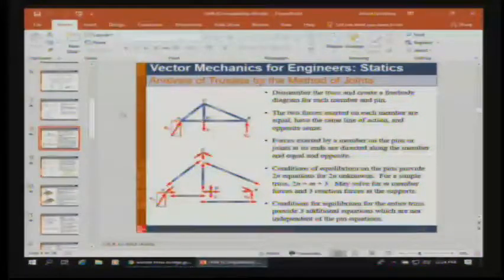All right, so when we talk about the analysis of the truss, what we're saying is that if you look at a truss like this, every one of these structural elements, AC, CD, CB, DB, and DA, are all going to have forces acting on them, and the forces are all going to be directed along the structural members. So if we look at what's going on here at C, we're going to have a force pushing or pulling on C from this structural member, and likewise from each of the other members.